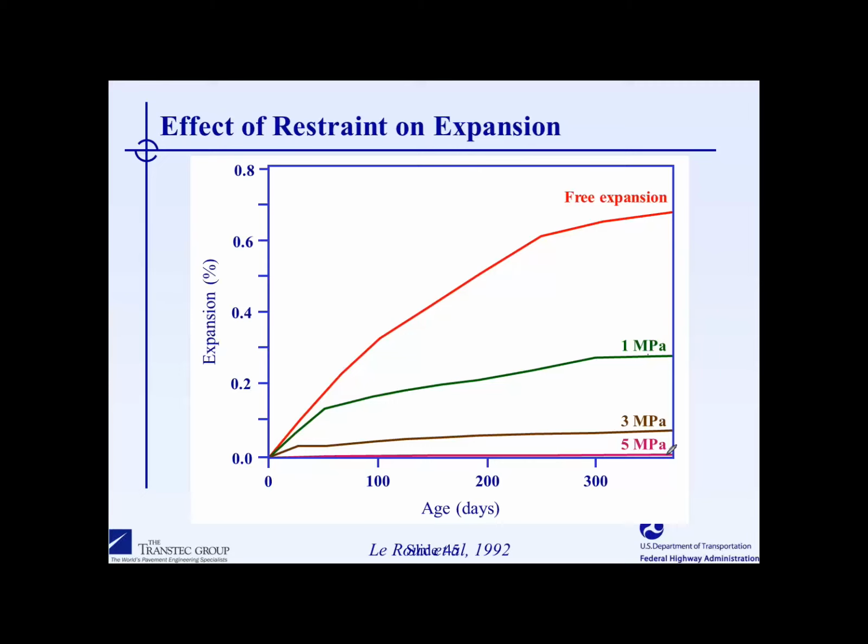Now, the more practical case here wouldn't be, say, applying a vertical load to a concrete structure to prevent ASR, but rather if one has a concrete column, the question would become how much lateral confinement you would need, say in the form of an FRP wrap, in order to stop the concrete from expanding in that direction.